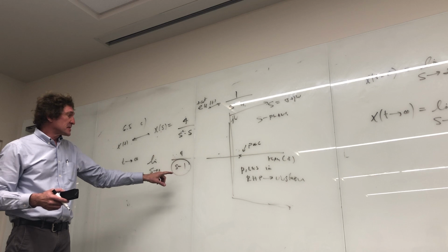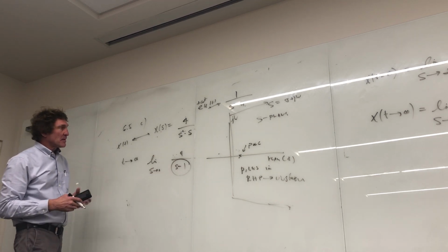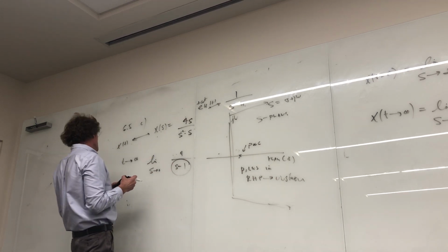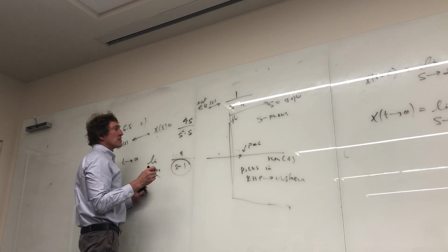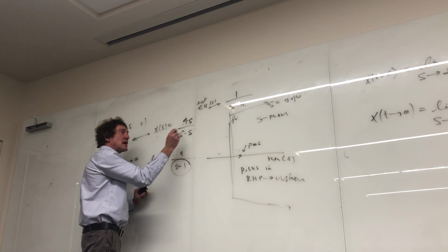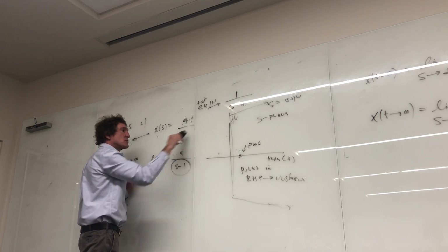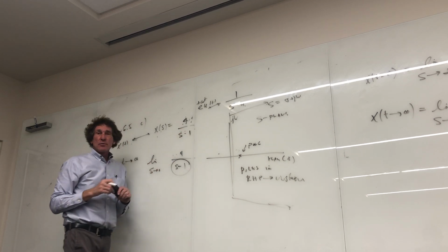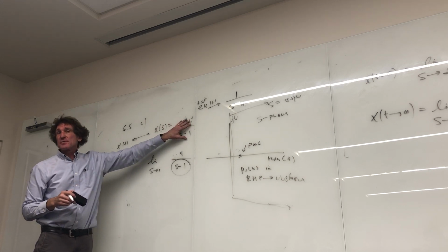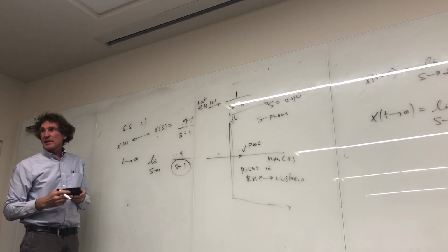It's because the fact is that pole's in the right half plane. And unfortunately, when you do this one by rote, if you multiply this by s and take the limit as s goes to 0 here, well, if you didn't do any manipulation, I would have 0 by 0, and that's undefined. If you manipulate it, you get s minus 1. Now that does not go to infinity. That goes to minus 1/4, and it doesn't reveal the nature of this. So the only way you can see is by a pole plot right there.